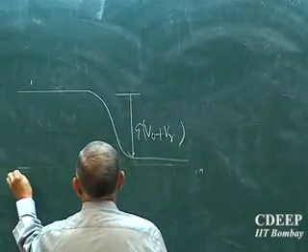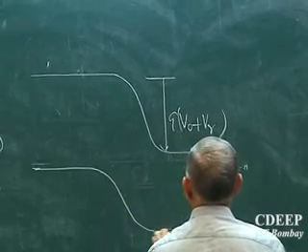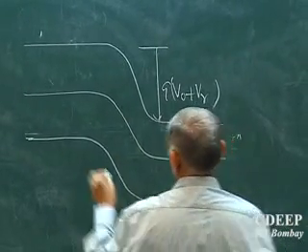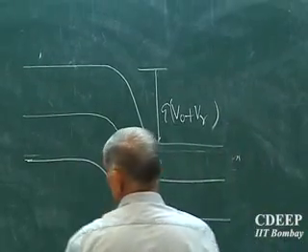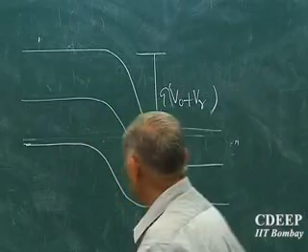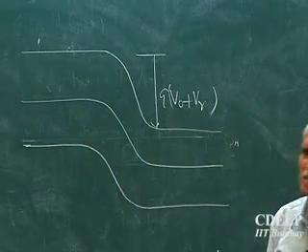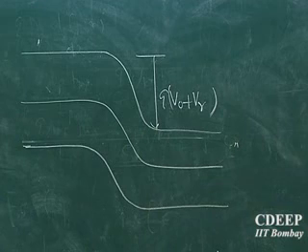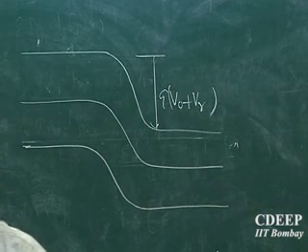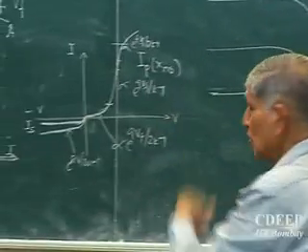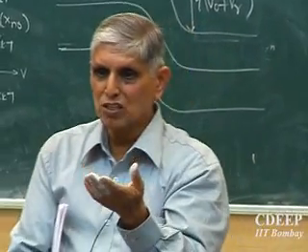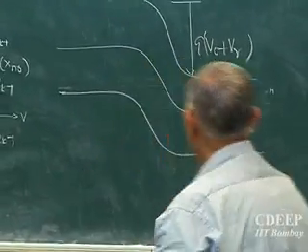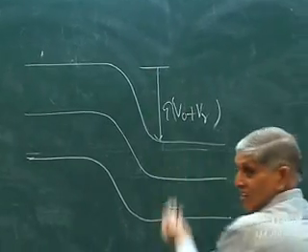First let me draw the figure and then we'll see where this should occur. Okay, please remember where the Fermi level of P type and the Fermi level of N type are. If I increase the barrier, that is, I apply negative potential to P and positive potential to N, electron energy in N will decrease or increase? Just look, when it was positive potential, what happened to the electron energy? It decreased. Now what has happened? It has increased. That means the electron energy is higher on this side.